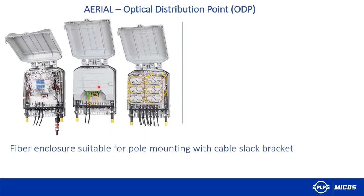And now it's time for the second group. It means the customer says, I want your service. They send the second group, which is less technically educated, and they don't have a splicer. So they just come with a drop cable, deflorate the grommet, make a little slack, and oops, connect the customer. That's it. This is the most popular way nowadays that home passes are connected with this type of application, because it's quite well designed, and in the real field the installation is very fast.